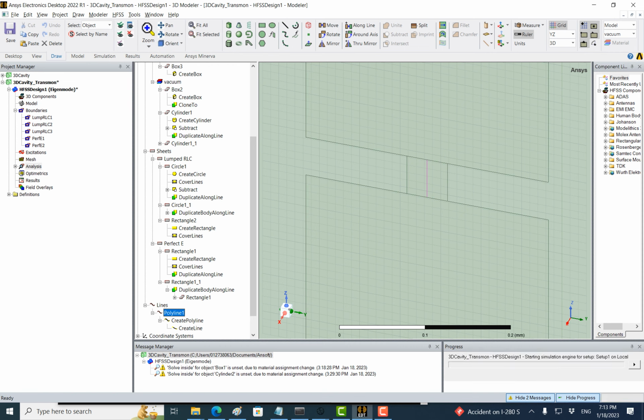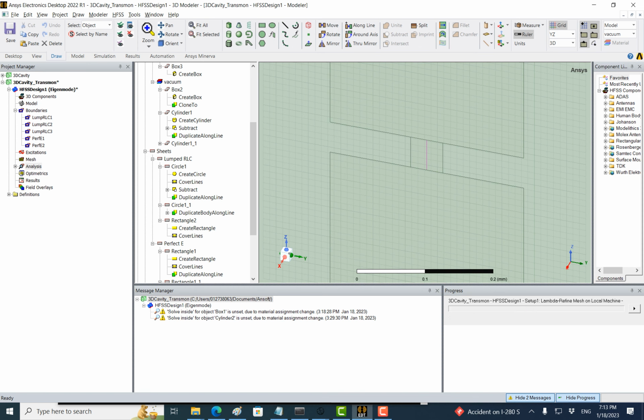Right, so then you will start the job, and as you can see on the lower right, it starts running pass 2, pass 3. In each pass, it will try to refine the mesh, so as to get it more and more accurate, right? And obviously, even up to 8 passes it is still not converged, right? But that is okay. Actually, you see that it converges eventually at 8 passes. How do I know that? I'm going to go to this result.